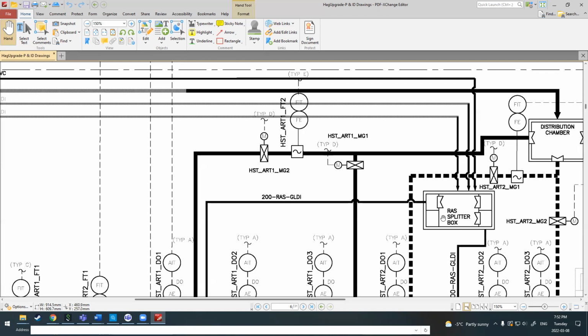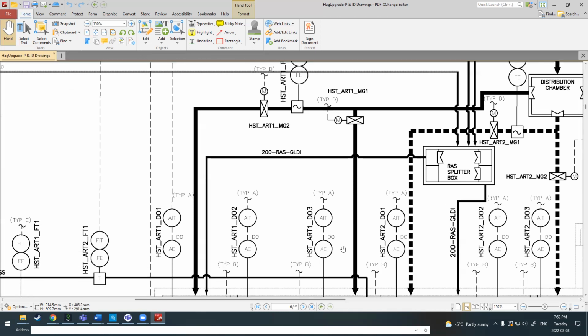So in this case, you can see the process breakdown, but you don't know exactly how this weir is installed. You'd have to go to the mechanical or structural set or portion of this drawing to see how these are installed. These could just be fixed weirs, or they could be adjustable. Here you can see that there's a motorized aeration. So this is MG. So this is maybe a gate, or maybe it's an air valve.